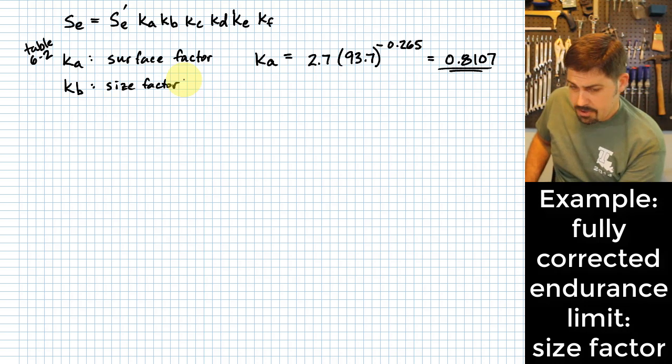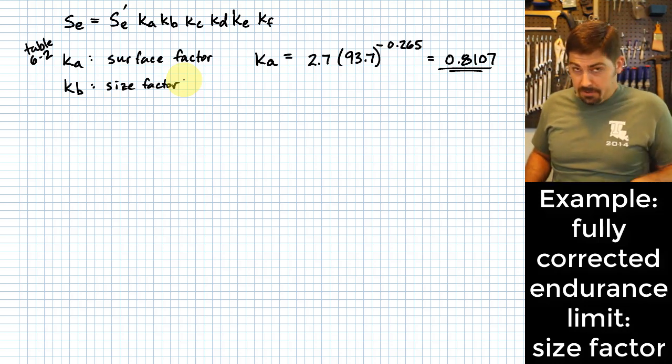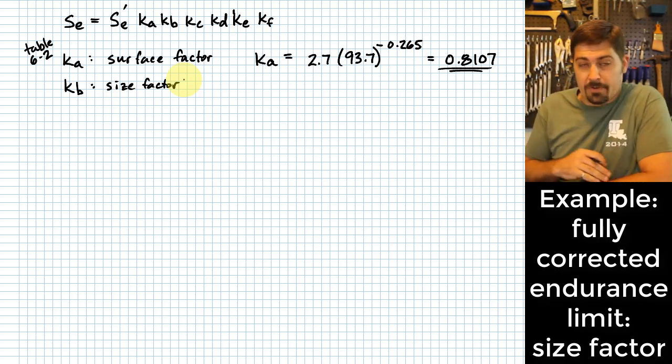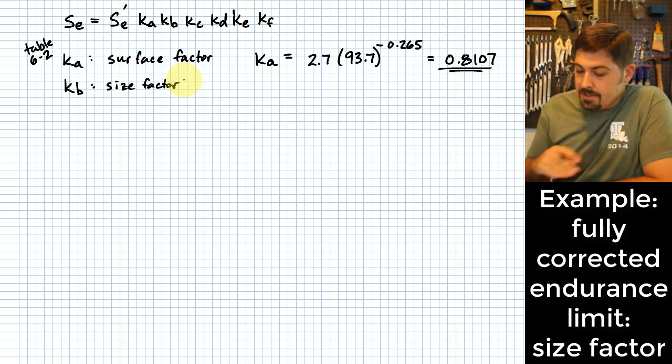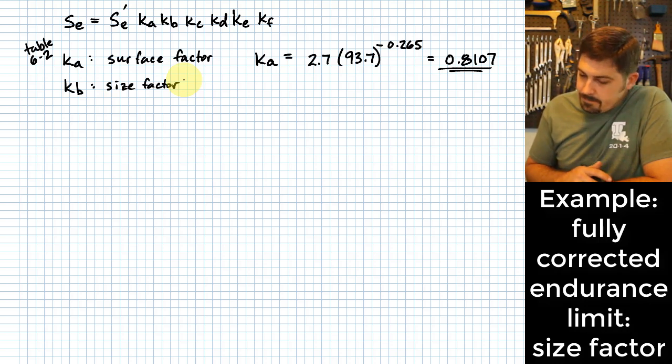And so the larger amount of material you have that reaches high levels of stress, the larger number of potential sites that you end up with where you could initiate fatigue. And this factor basically takes that effect into account. It does give a little formula in the book for round, rotating bending type of things, which is exactly what we have, so that's nice.